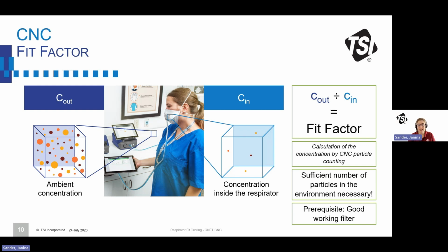In the case of a good fit, we have lots of particles in the ambient air but just a very low concentration inside, and then the fit factor is a high value. The more particles we find on the inside of the respirator, the lower the fit factor will become, and therefore the less good the fit is. So the lower the number, the poorer the fit.